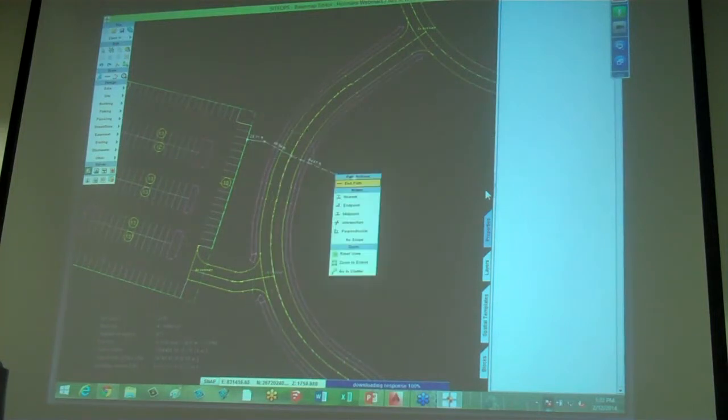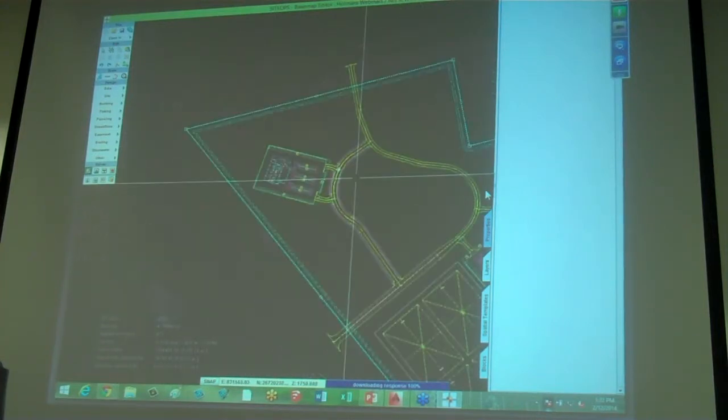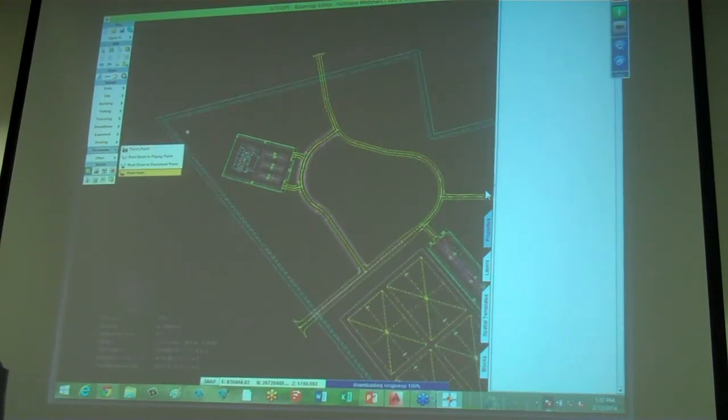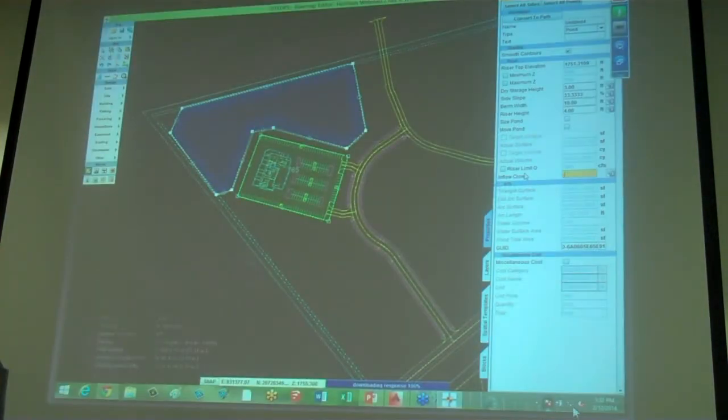And again, very simple. I've added something. Let's go ahead and add a pond. You can add stormwater. Let's go shoot a few more tools before I start doing things. Now again, software, it doesn't care if it's a dry pond or wet pond. That's ultimately up to you as designer. What is my inlet controls? What's my size? Do I need to size this pond based on target surface, target volume? Again, all those things I can start doing very simply.